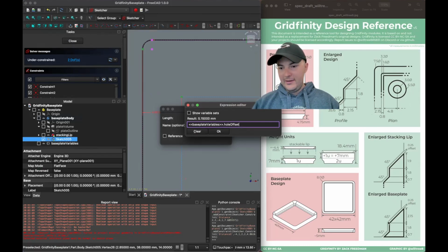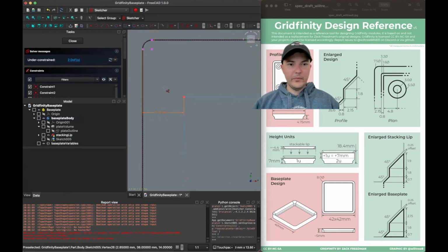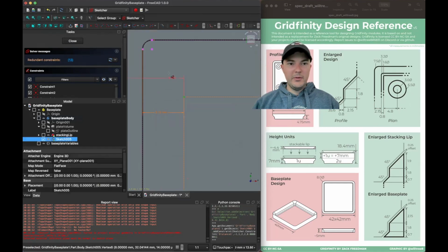This is the offset that your Gridfinity container is supposed to be for the base plate. Now I don't exactly know why in the assembly, but it's true that you need to add not 0.25 millimeters, but 0.35 millimeters for there to be a proper hole lineup. If somebody understands the trig, please tell me.